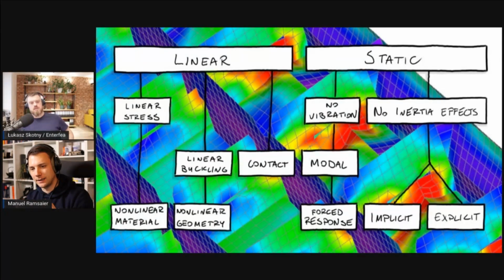We will do a linear buckling, take the shape of a buckling mode, apply that with a scaling factor to your model, do the imperfections like that, pre-deform it, and then apply the loads for a linear subcase again and see how the stresses behave. Would that be a thing to consider for imperfections?